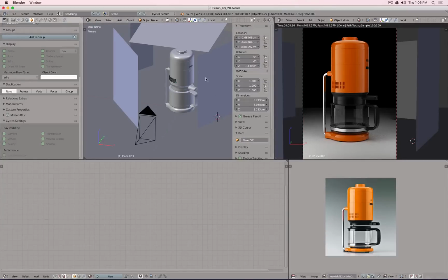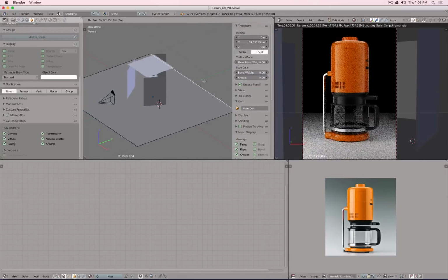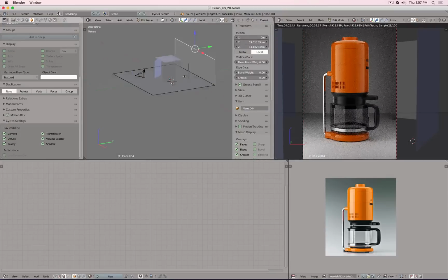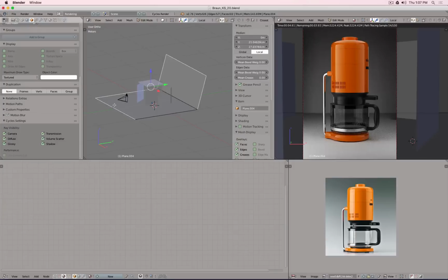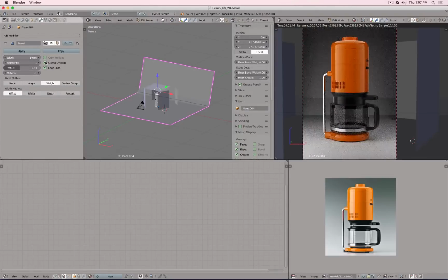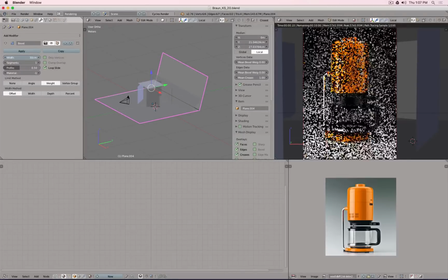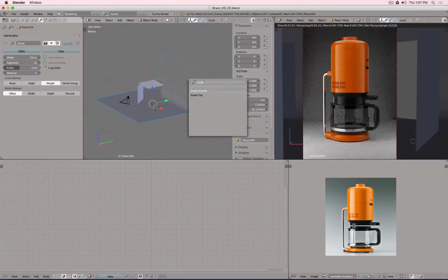There's a backdrop, as we can see. So let's make a backdrop. And maybe move this one up. There we now have a very basic wall. Maybe to there. This edge I will actually weight with a bevel. And then I will select all these edges and Shift E and crease. Now when I add a bevel modifier, I could say use the weight. 1 centimeter. Now I can define how big at the end it, for example, arcs, and maybe how many steps, maybe 16. This whole object should look smooth.